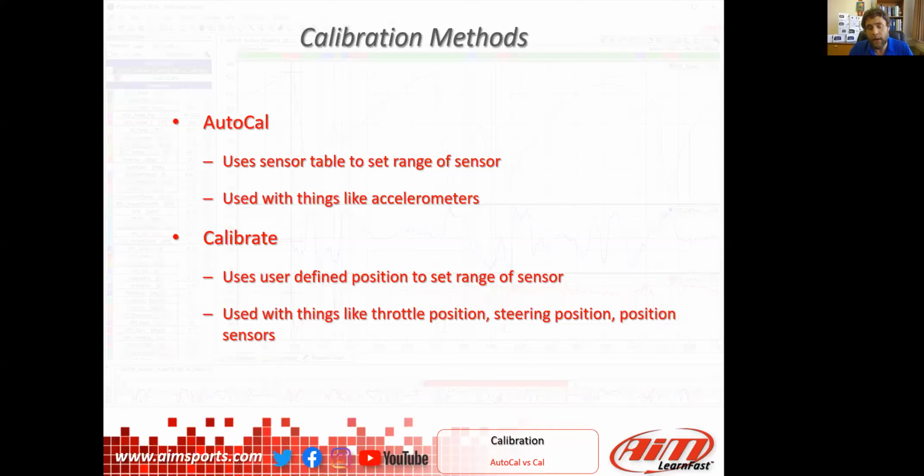But it all comes down to what you're looking at. To get really deep into it, you start looking at different problems in the data and the signal and how it combines. But I think Roger's document's got it good. Looking at driver inputs, I'd say 20 to 50. Chassis things like suspension, 200 to 500.